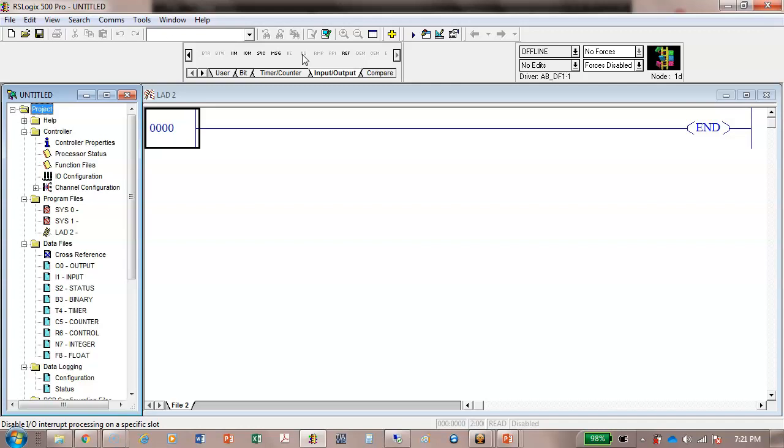So first thing you do, no matter which application I've ever programmed, is select, well, that's not true. Normally, and this is backwards for RSLogix 500, notice I did not give this program a name. RSLogix 500 is not going to require a name until you download it into the PLC, which is very strange, or you save it.